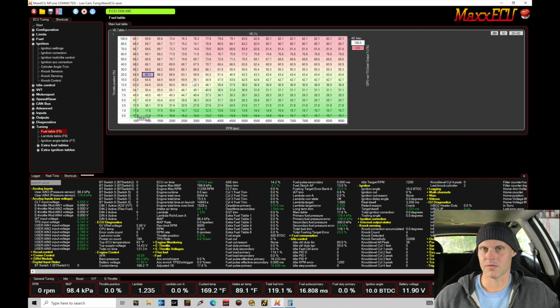We're in our volumetric efficiency table here to begin our tutorial, and this is what we found worked for our low cam for this Alpha-N strategy. Now I want to be able to take this table and bring it into my high cam. So we have two different VE tables. We're going to find here we have a 4D axis separating our two VE tables. So when we're on 0, we're on VE table 1. When we're on 100, we're on VE table 2.